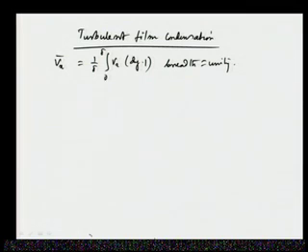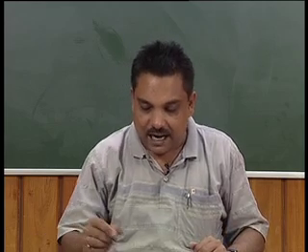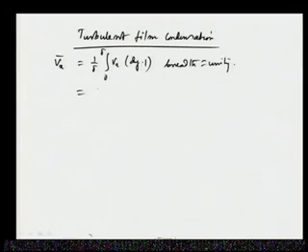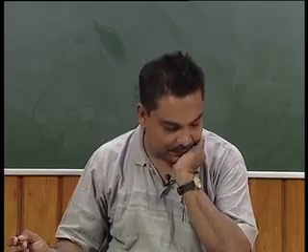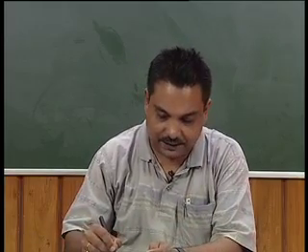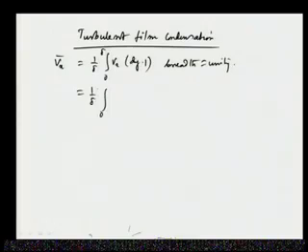Divided by delta into the unit area, this is the volumetric flow rate divided by the area, integrated, so we get the average velocity. This uses the velocity expression we have found for vertical plates, and if we put that expression over here, we get 1 by delta, 0 to delta, then (rho L minus rho V) into g, based on the velocity profile we have assumed.